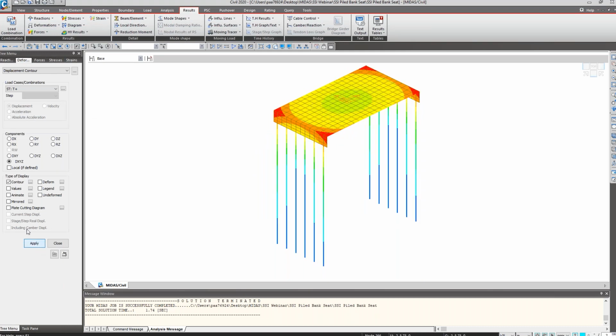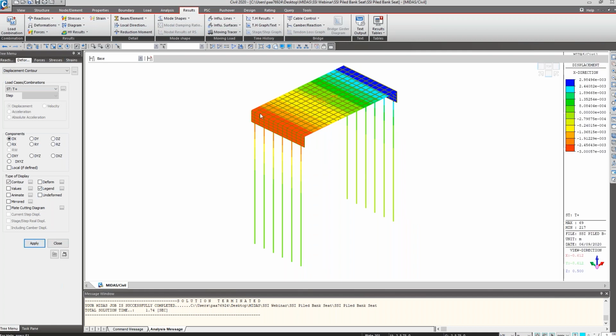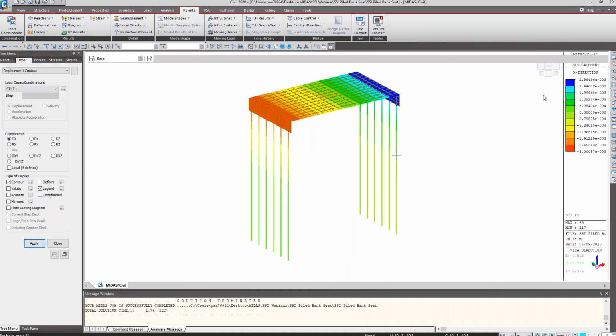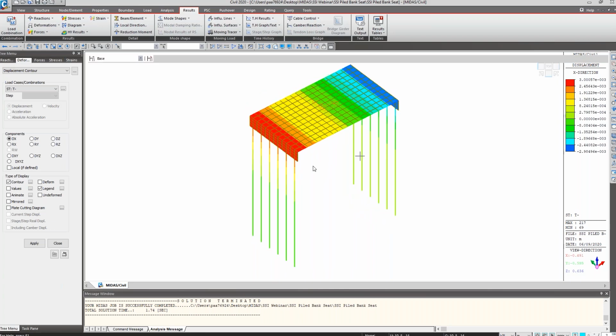And for instance, for expansion, just the displacement in X direction, and we activate the legend to see the values. We see that basically this expansion contracts 3 millimeters. So this is expansion 3 millimeters here, but we check T-, we'll see that this contracts 3 millimeters as well.